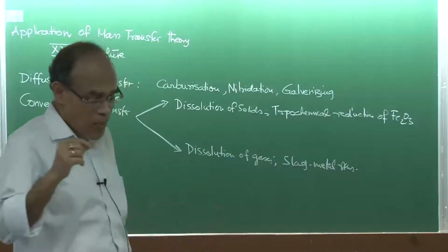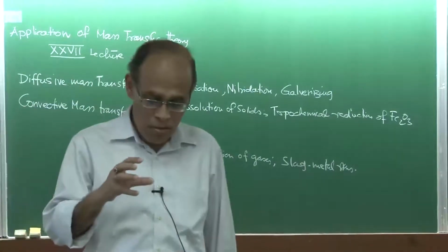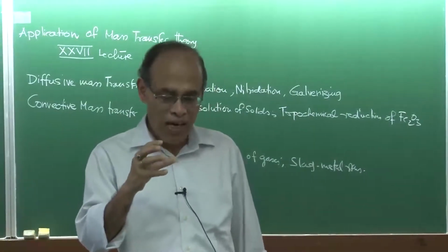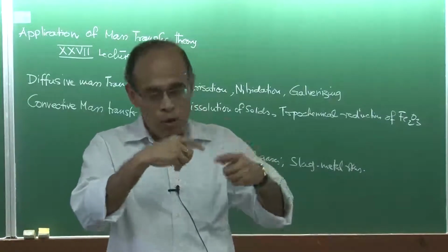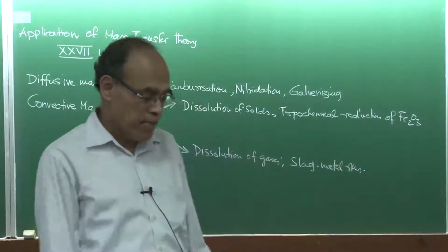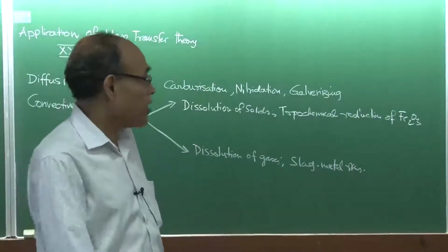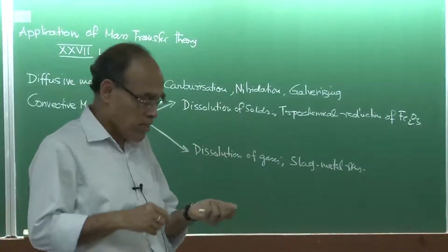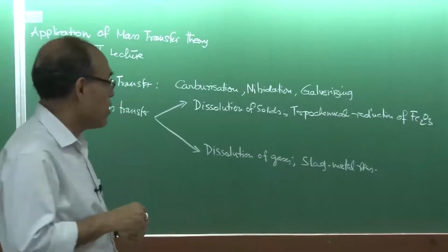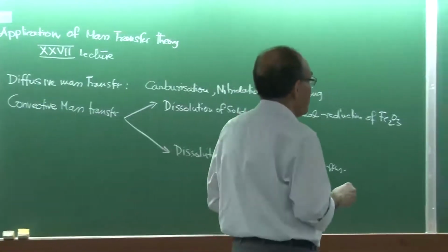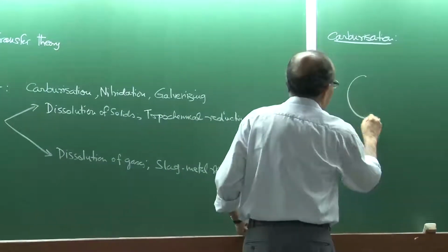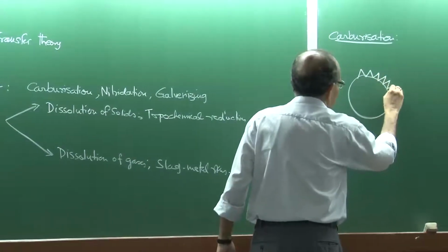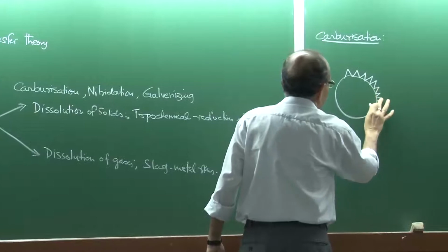So it is demanded that the bulk hardness, if you use the bulk hardness of steel, that may not be suitable because of the large friction taking place at the point of contact. And therefore, it is warranted that the surface be at a higher hardness.